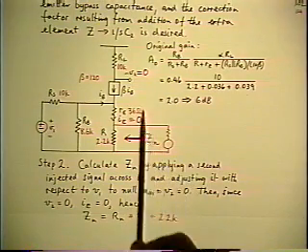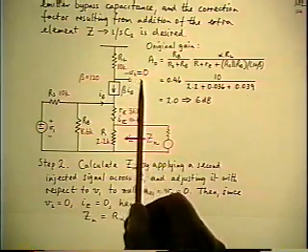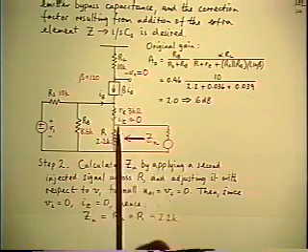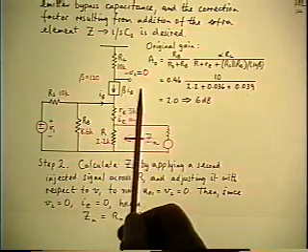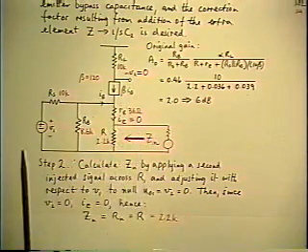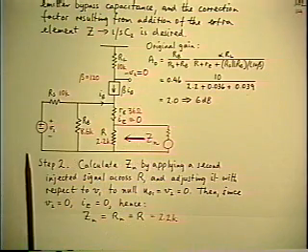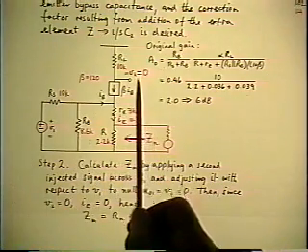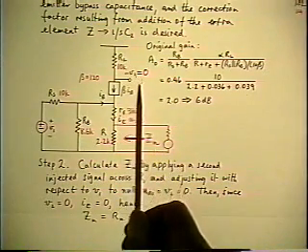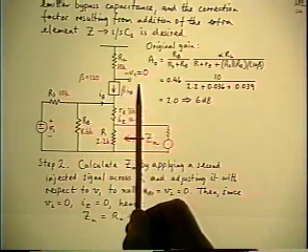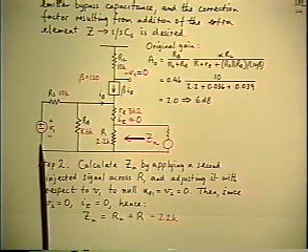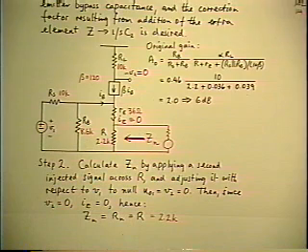The equivalent piece of information is the null. That's what was used. Then we propagated the null, which is using the fact that the null exists. That's what took the place of the knowledge of V1, because there's a unique relationship between V1 and the second source that produces the null. So if you know a null exists, this is the same thing as knowing what V1 is. You don't need both. It's the same information.